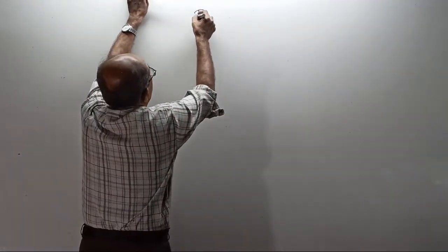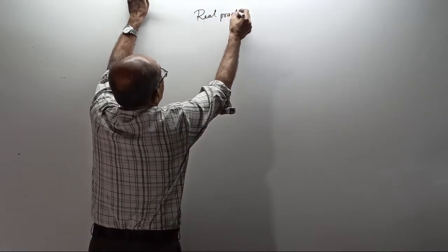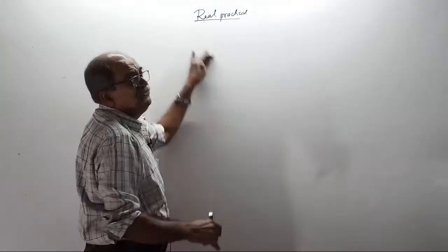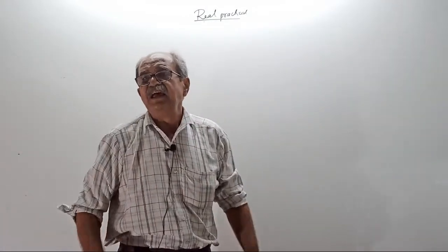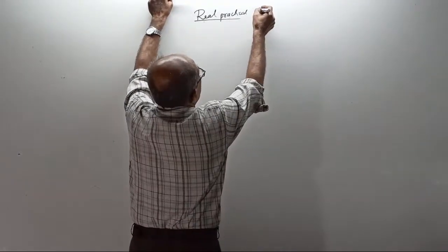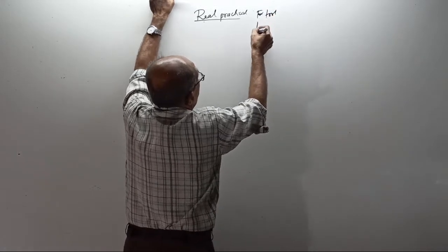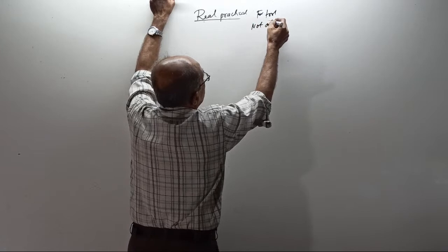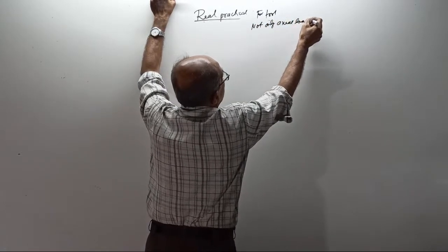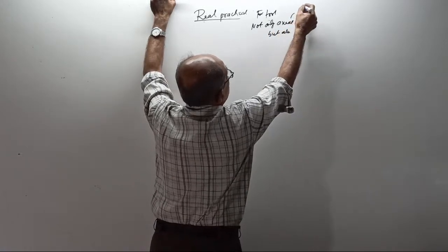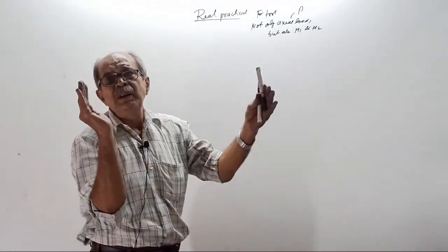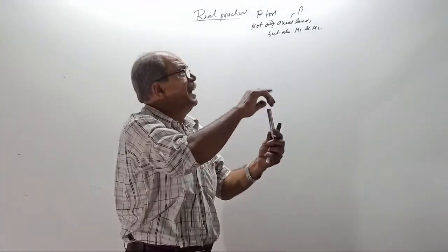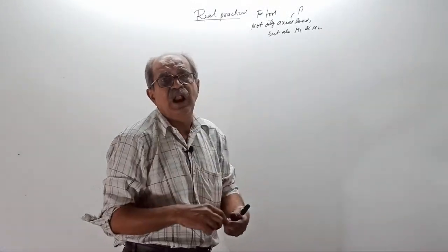Now, completely fresh. Remember, make a note. Real practical. Then some will ask you, sir, what is that one bogus, sir? No. Real practical means you are entering real practical design. Everything told so far is the foundation for understanding. Now you develop the real practical. See, that is for the footing, not only axial load, but also axial load is P, but also M1 and M2. Now, M1, M2 means one bending or couple this way, and M2 lengthwise. M2 is widthwise. This I told you for column chapter, or I will show you now.